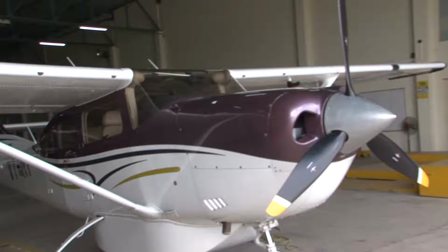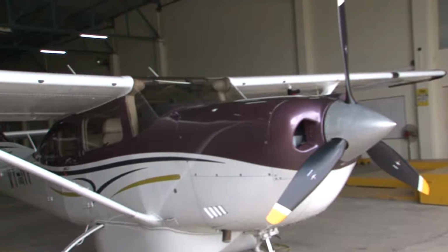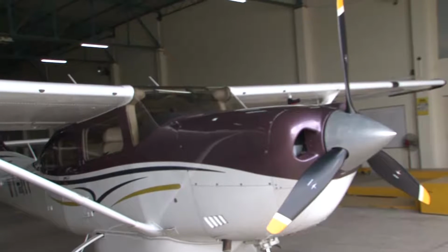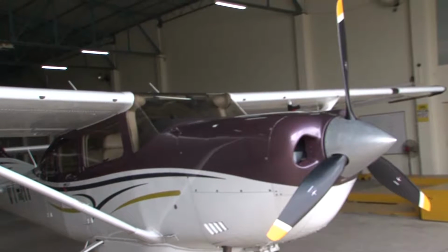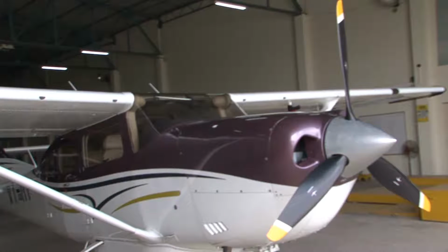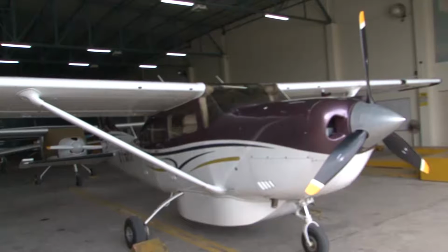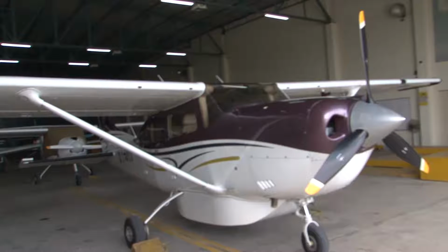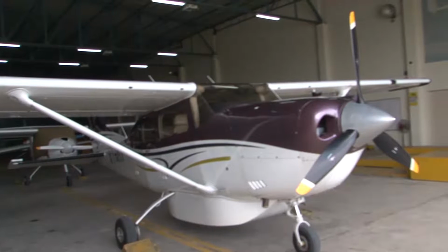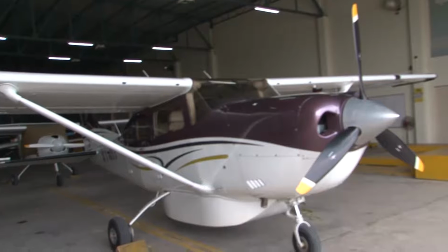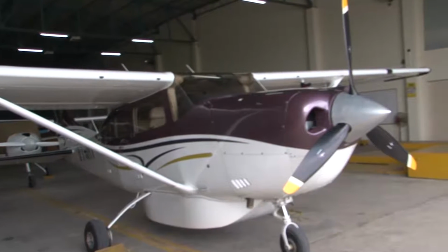And now you can check from the statistical data for general aviation single engine aircraft, the wing loading will be around 100 kg per meter squared. So once I see this, immediately I cannot avoid looking at the propeller. One thing I see first, there are three propeller blades like that. There are airplanes with two propellers. It has its own stories in terms of efficiencies and power being delivered.